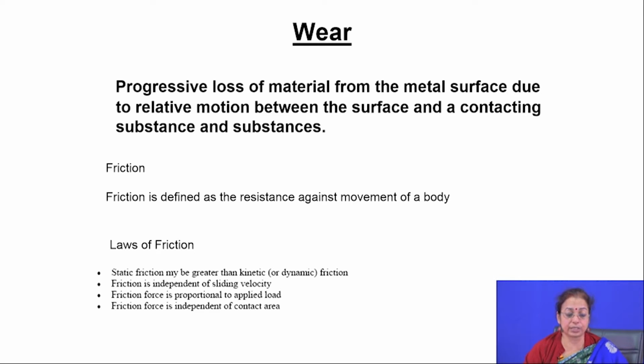Coefficient of friction is very important in any wear phenomenon, especially when the wear is adhesive in nature. It is defined as the resistance against movement of the body, and it is very much dependent on the meeting surface and also the media.